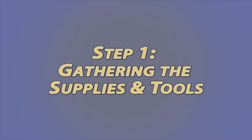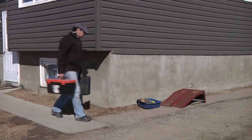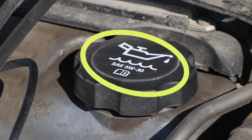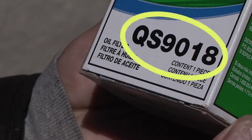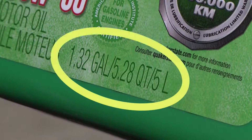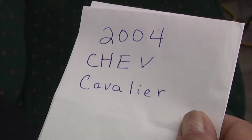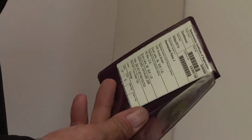Step 1. Gathering the supplies and tools. In this step, we will be gathering all of the supplies and tools needed and recommended for an oil change. We need to find out the oil weight, type of oil filter, and amount of oil we need for the oil change. You can find this out by checking the owner's manual. If you don't have an owner's manual on hand, contact your local auto shop to find out what oil and filter you need. Provide them with your vehicle model, make, and year. You can find that information in your vehicle's registration.